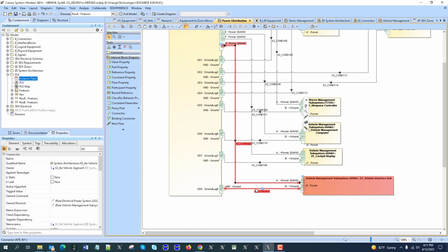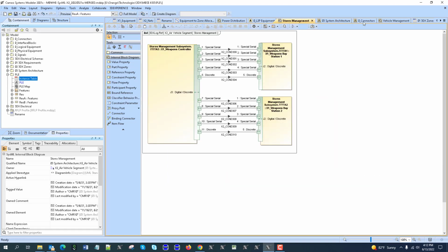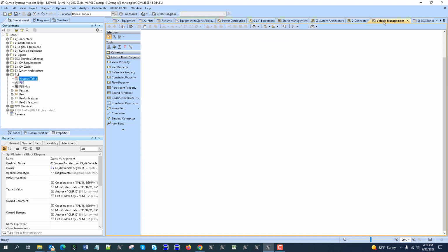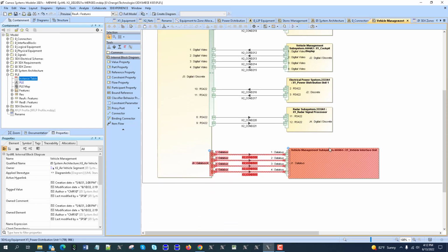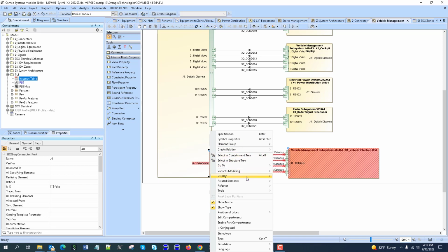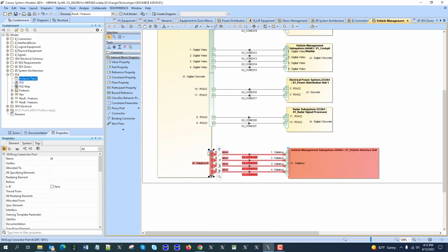This one we physically added the existence because only this part was removed, right? So the port stays in the model in general, and this connector might also stay. That's why we are removing it. Then from this view, we don't have any variation points. Here we have some of them. Here we have this component also removed. It's the same one as in the previous view, and those connectors are also removed, and also this port, as you can see, with modeling existence. Because this port will disappear, those will disappear automatically.